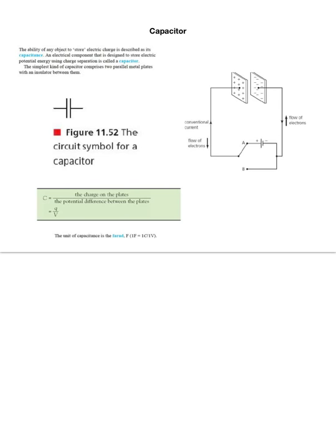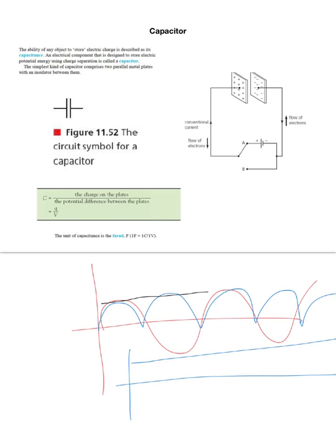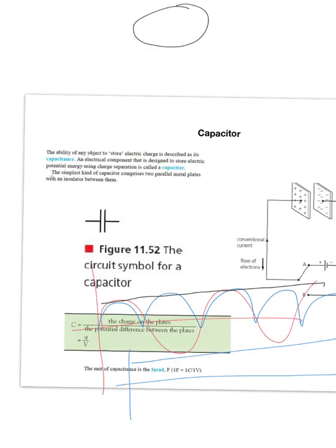So how far are we in our rectification? We've gone from this to this. It's not quite DC yet because we want something like that. Okay, so we've still got one stage to go. We need to smooth out the lines, try and make them go as straight as possible. So that's what our capacitor is for, and that's our next little component.